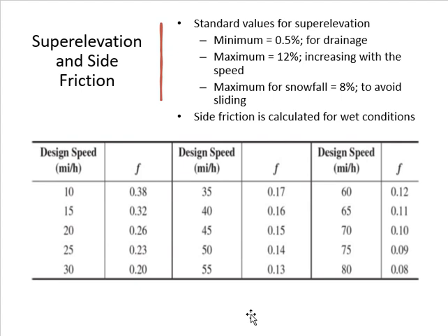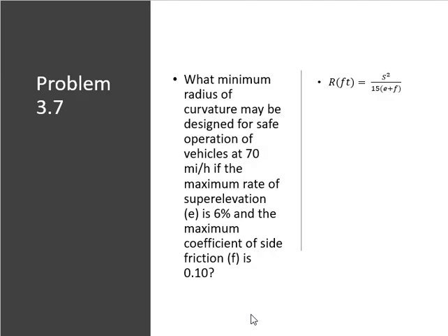Okay, and in the highway course there was a question as well, I believe, where you were supposed to find out the coefficient of side friction using some data from driving. But in any case, f can be found in the lab or from the road. We have this table which they have provided according to the speed and normal surface of the road.